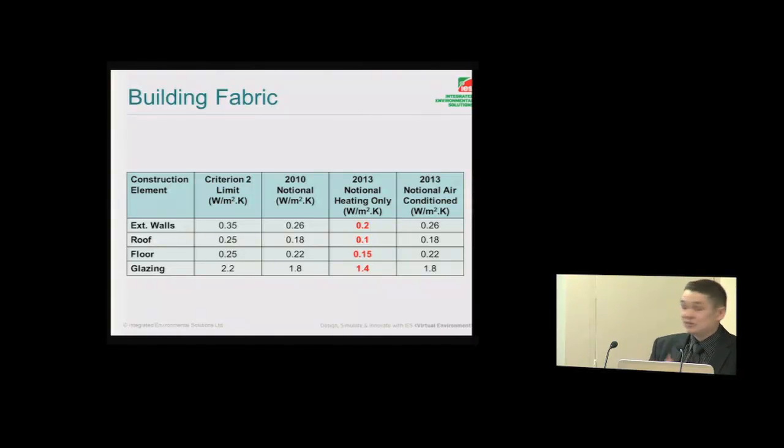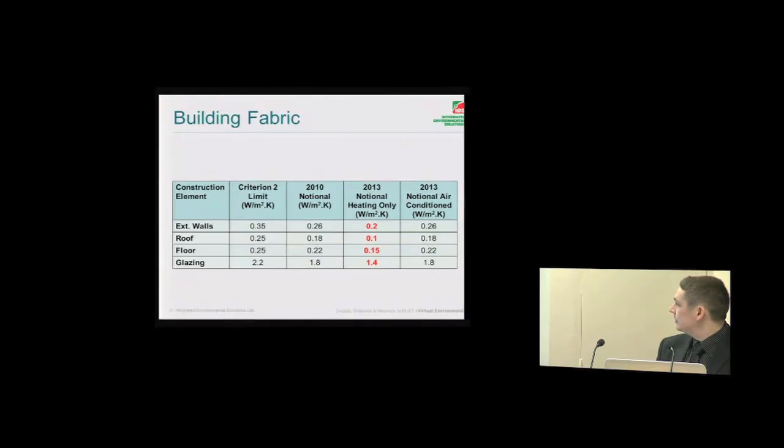Do you know what the thinking is behind the higher U values for your... I don't know for sure. What I would expect is that if the building is going to be dominantly heated, it perhaps makes sense to have it better insulated than a building where cooling is going to be dominant.